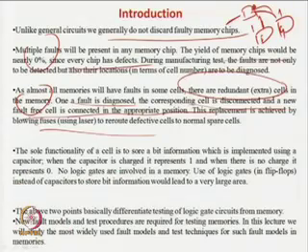So, what you have to do, there should be a multiplexer kind of a thing. These are muxes. So, this is your input. This corresponds to 0, and this corresponds to 1. You should always ensure that the input never goes here, because now it is faulty, the input should always go here. If you put a 0 in the select line of the mux, data will go to the normal part, which is normal as of now, and if you put a 1 in the select line of the multiplexer, data will come to the faulty part.